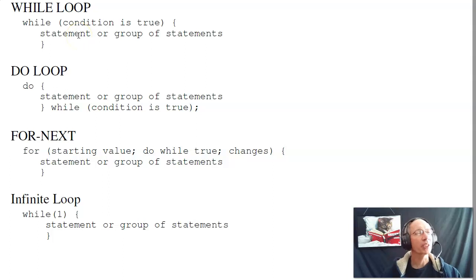That's actually really common. In embedded systems, you typically have a loop that runs over and over again. For example, if I build a stoplight, I want the stoplight to work over and over again. I don't want it to work just once. So there's almost always an infinite loop in your code. Sometimes you'll have a while loop, so do the following, like while the button's being pushed. A do loop says do the following and then check. A for loop is typically like for I equals 1 to 10, do the following group of statements 10 times. And an infinite loop, like I mentioned.